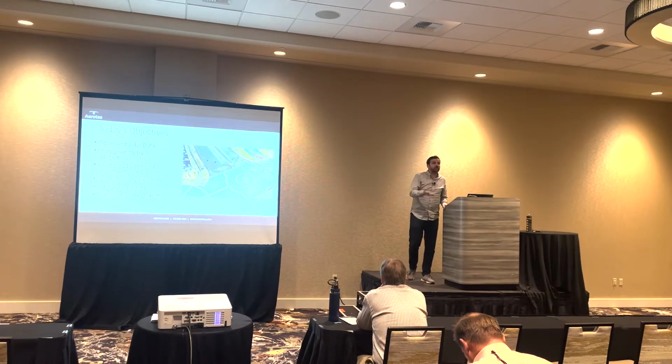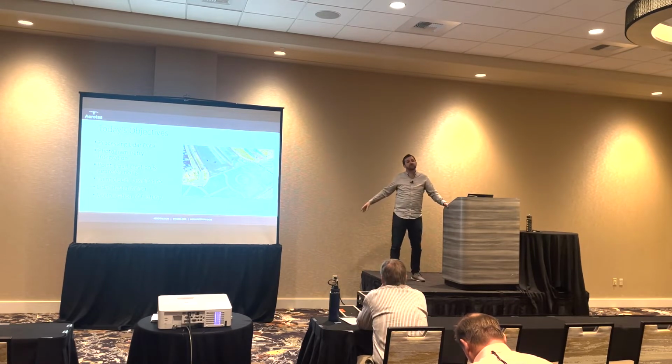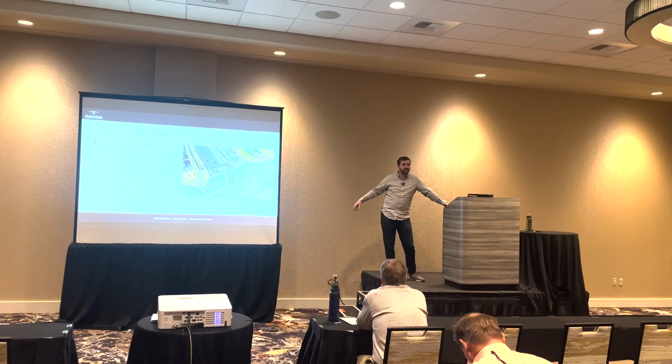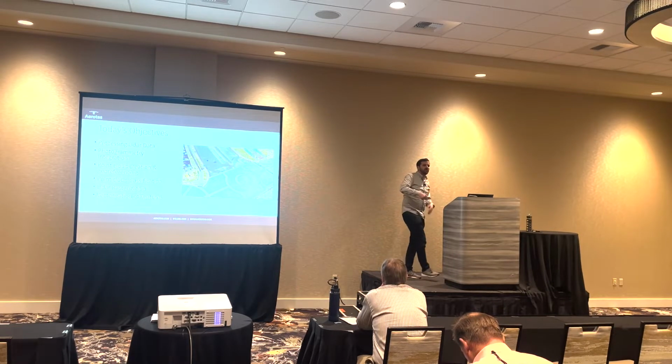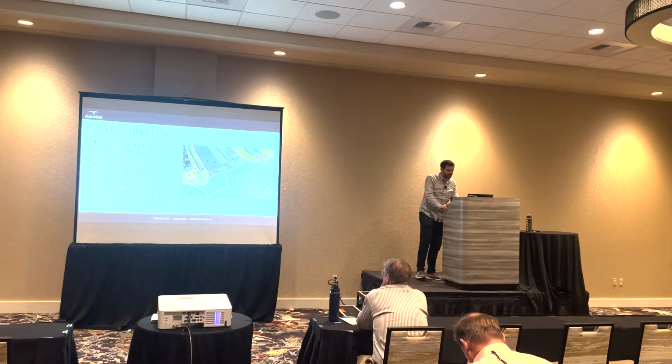But yeah, that's one of the wonderful questions. Raster versus TIN surface for surface data. They both have their applications, they both have their uses, they both have their trade-offs. For us, TIN surfaces are preferred, a vectorized TIN surface is our preferred format, but often to get there you need to use a raster surface as an intermediate. We'll cover that in a lot more detail, but great question.